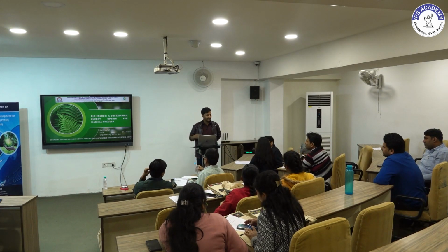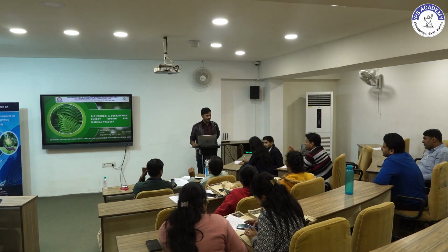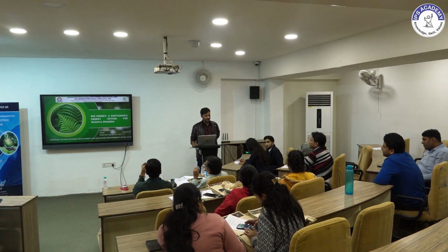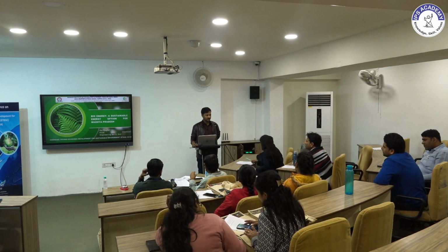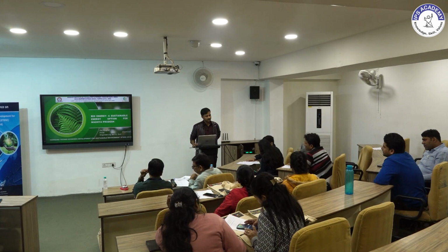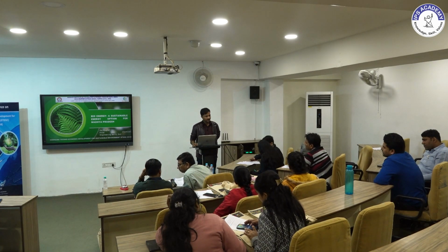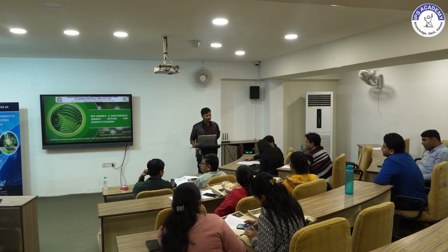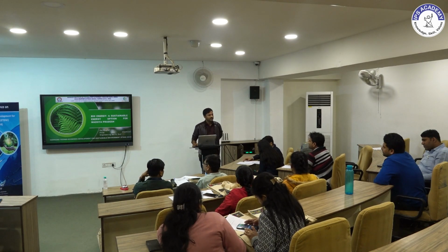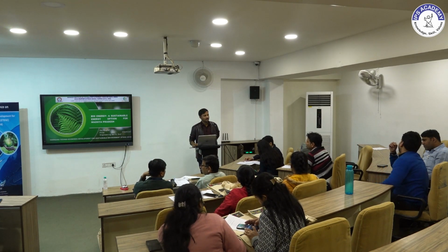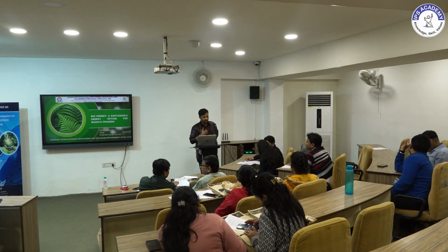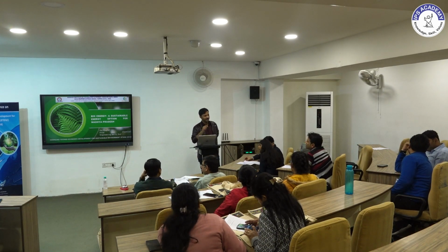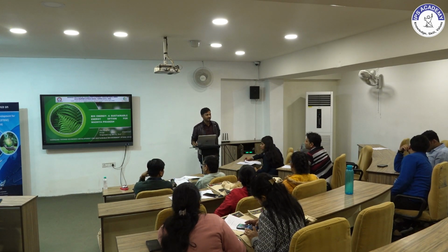Yes, sir. So you should write 300 to 350. Slow pyrolysis. So the LDPE is degraded at 350? It will, because for LDPE the maximum degradation temperature is around 420 to 430. Sir, actually we have a coil heater, and it mainly maintains that temperature.